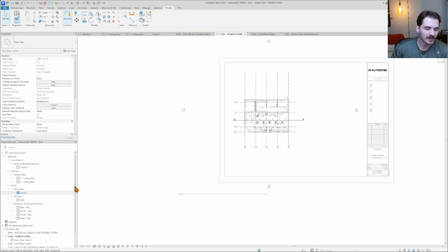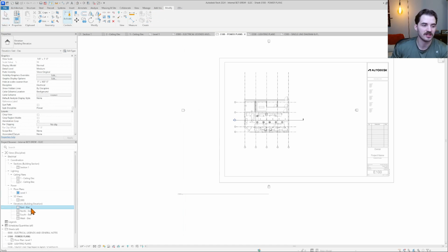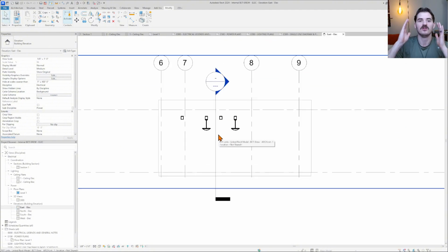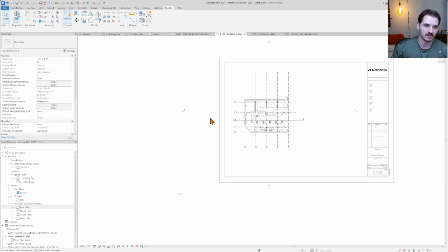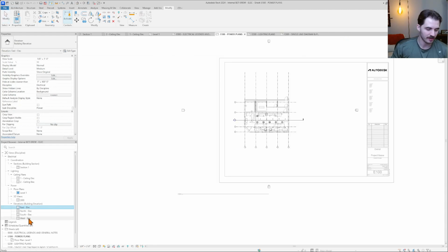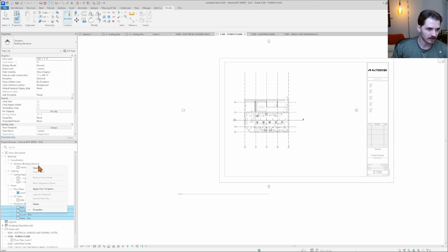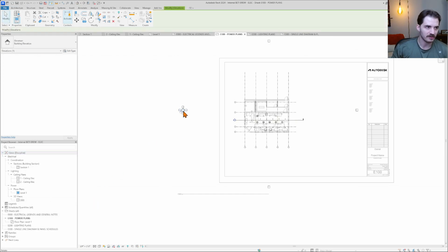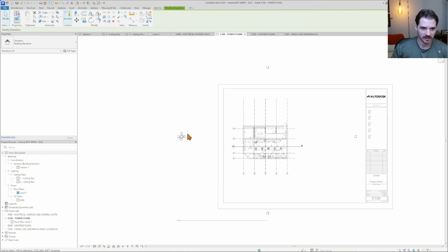So actually, this is something that Revit also created when we used that default template, these elevations, which I can click over here in my project browser, but it's just showing an elevation view or a section view from the east side of this building, which we really don't need, and it's just bogging up our model. So I'm going to shift click, right click, delete all these elevations, and then these still exist.